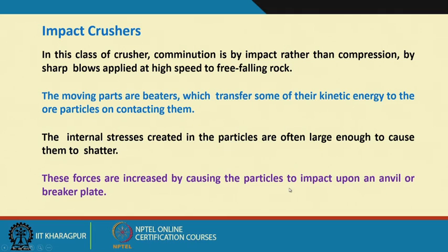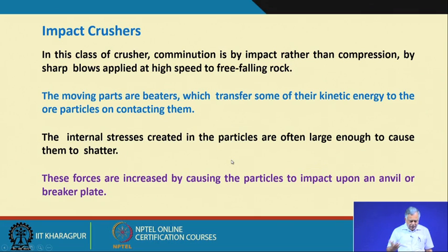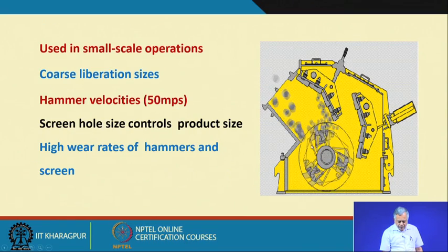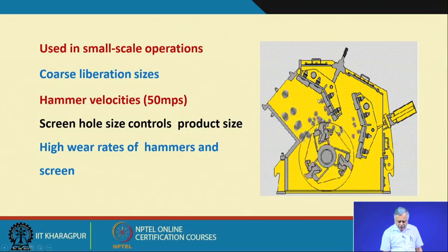These forces are increased by causing the particles to impact upon an anvil or breaker plate. So, that is the beater, which is lifting the material, and then the breaker plate, the rigid surface that you are hitting. Those are basically your hitting surfaces, which cause the breakage.